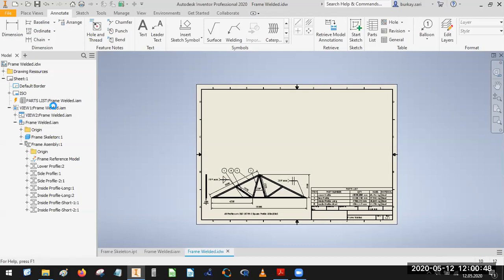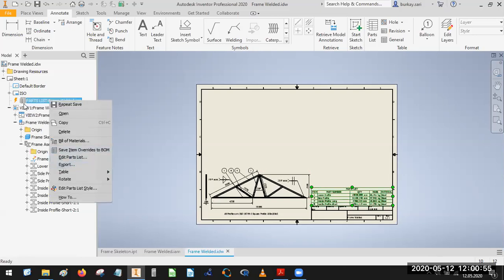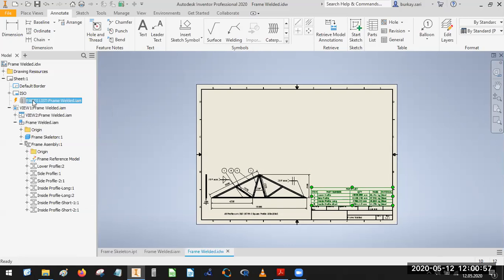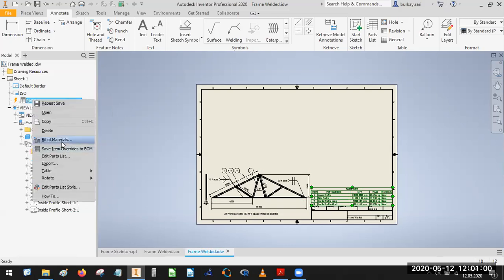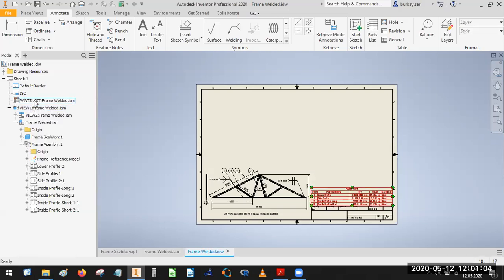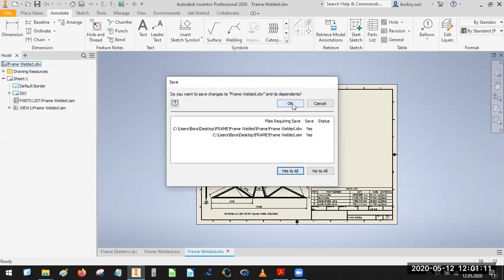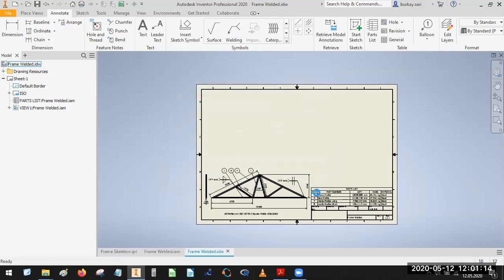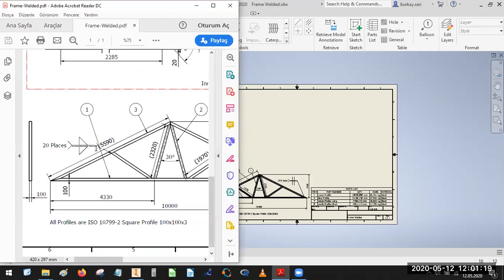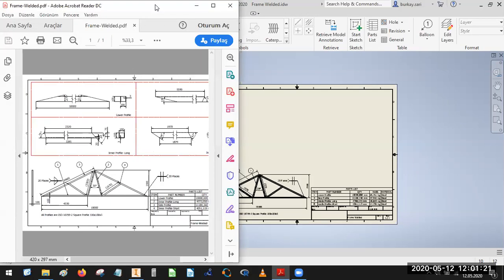As you see, also the part list here is going to be updated so far. Save the override items to bill of material. With right click, you can just ignore that save because we have overwritten and changed the properties from the original one, and we save our part. The next thing, we would like to separate our part files.